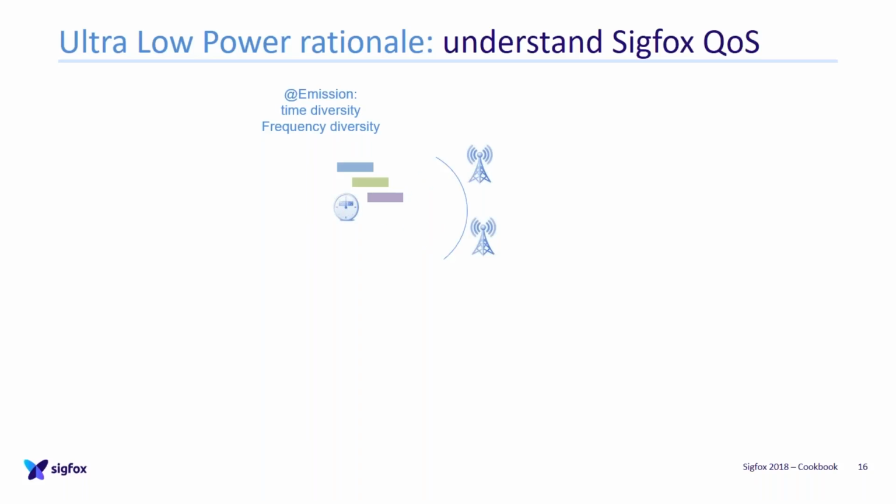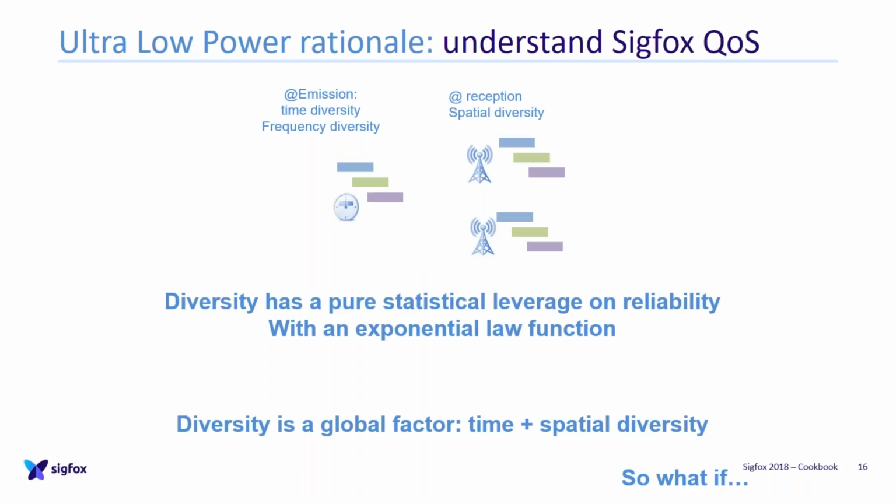So the way we have engineered the quality of service in Sigfox on top of the random access method on the air interface is as follows. We have models for the point-to-point success rate of radio access in the shared spectrum radio medium. The figures are not very good, of course. You're looking at a 60% success rate for a point-to-point transaction between one message issuer and a message receiver. So really point-to-point mode.